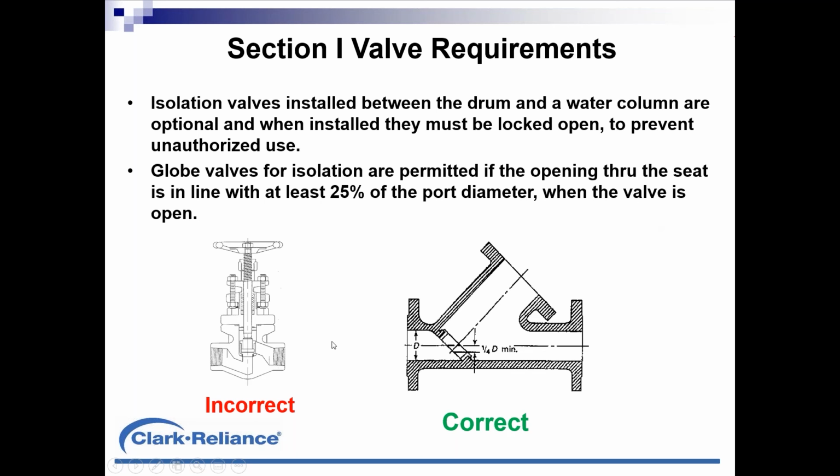This section view here shows a Y pattern valve, and this upward angle is where the operating stem would be. If the valve were loose and you were holding it in your hand, you could see light straight through this valve when the valve is open, or insert a rod all the way through it. So this valve is very resistant to sedimentation buildup or particulate buildup within the valve.